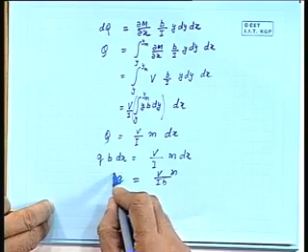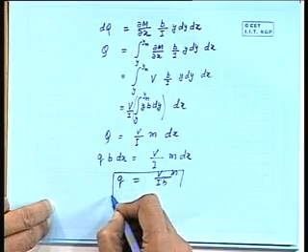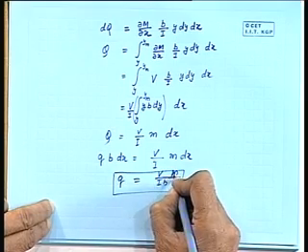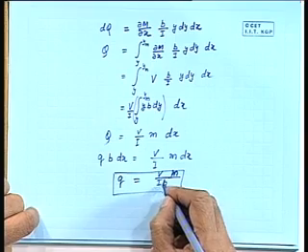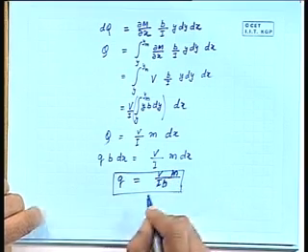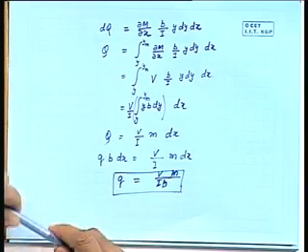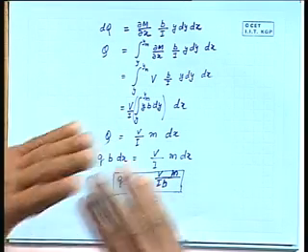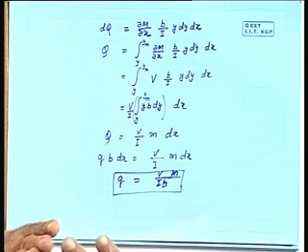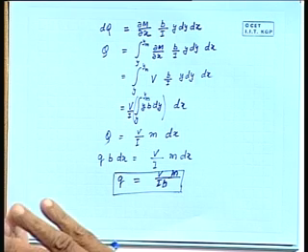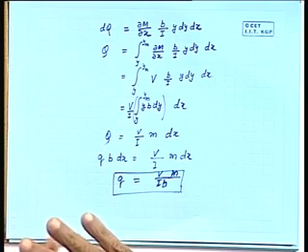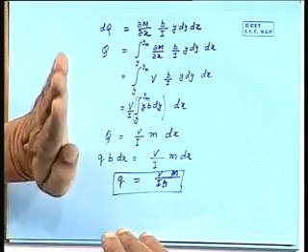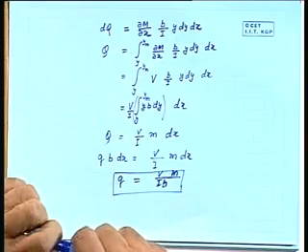So, this becomes the expression for the horizontal shear stress. Now, from the elementary strength of materials, we know that whenever you take a section, the horizontal shear and the vertical shear always appear in pair, this shear and this shear, and therefore, this q is also the vertical shear at that particular point. Okay.